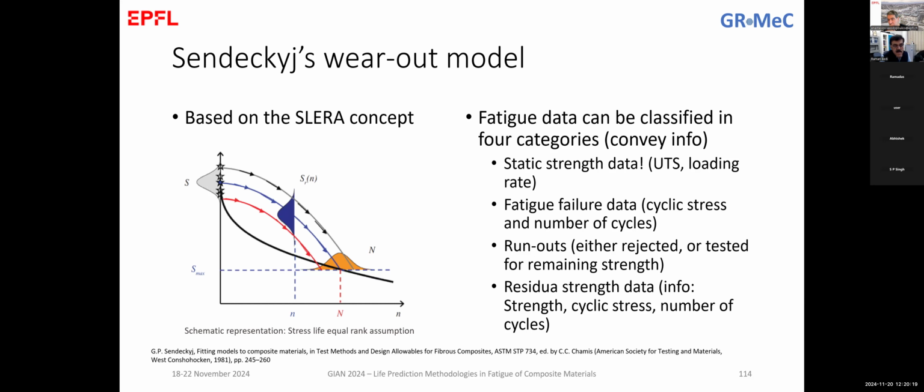I just have one question again. The SLERA approach has one of the biggest deficiencies, which is in the statement itself, that the specimen which is good in static strength is also good in fatigue. But we don't know. The one which has failed is already failed. So you cannot have the same specimen tested in fatigue and the same one in static. So in a way, there is again a big issue which I find every time. Because you have one specimen and it is very good in static test, but it has failed. So we don't have the same specimen. Exactly, you cannot break the specimen twice.